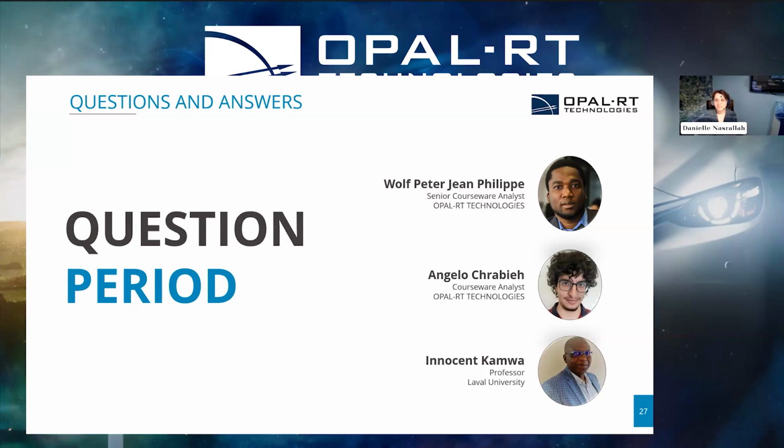I'd like to add two remarks. The first is that in RT Lab, we can do real-time power electronic simulation, even if the circuit is very complex, when we export a part of it to the FPGA. The power electronic solver in the FPGA is the EHS, the electric hardware solver. Once we export to the FPGA, we can move really fast and even simulate in nanoseconds. The second remark is that we are currently working at OPAL to render the HYPERSIM solver exportable within RT Lab.